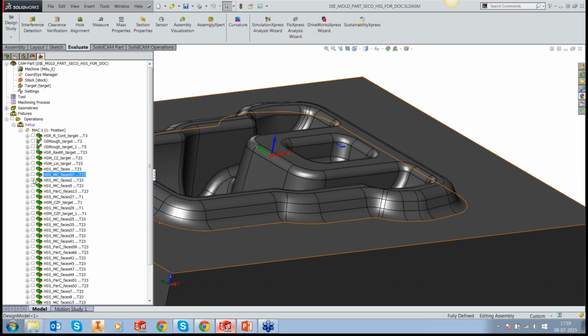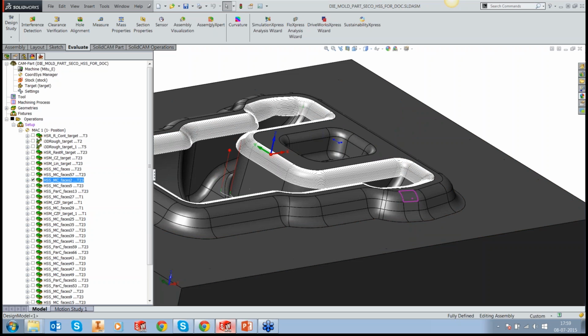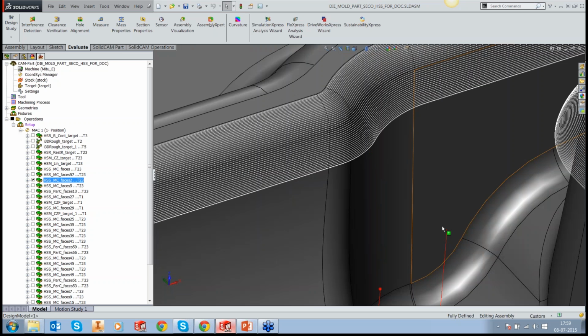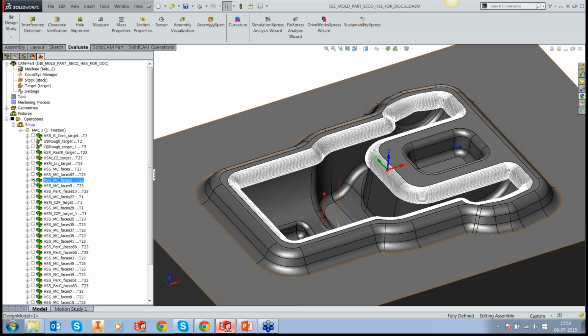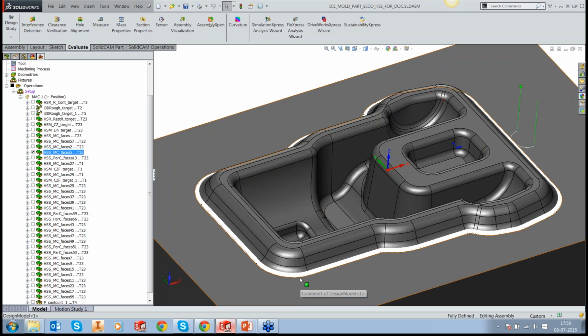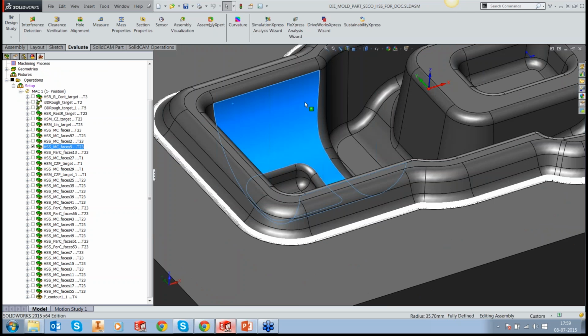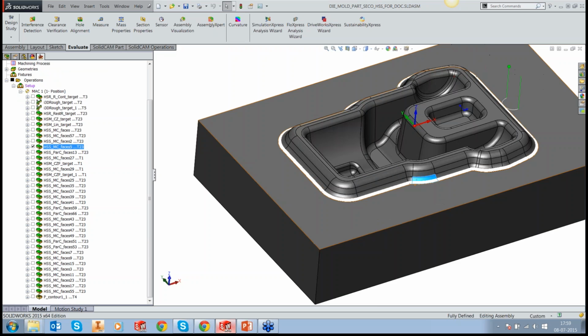And then the bottommost fillet inside. The fillet was machined inside. You can also look at the quality of the toolpath. It's very nice. And once the internal was done, we go on to the external side. There's another fillet out here. Sorry, that's this fillet that I'm marking right now. This is machined using this toolpath.